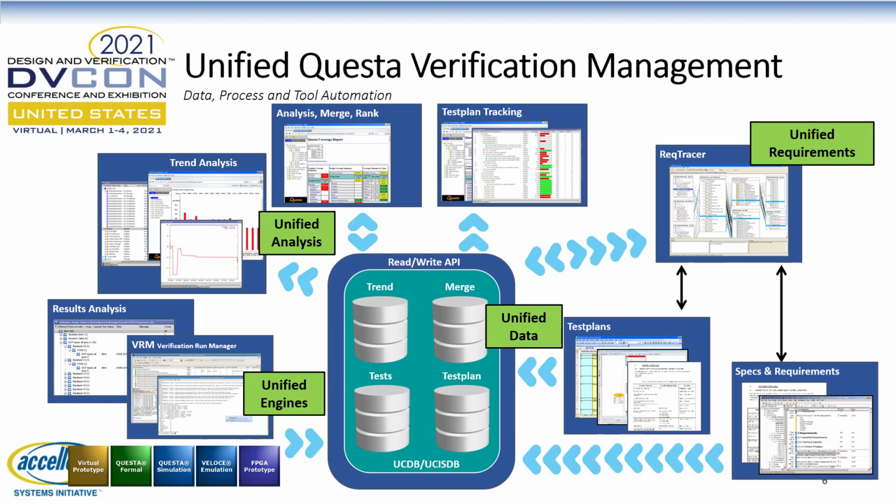And it also correlates elements of your verification environment to determine if that RTL element has been properly tested to satisfy the original requirement. The verification element can be a test, or it can be a SystemVerilog covergroup, or an assertion, or a UVM sequence, or whatever you need it to be. Since everything is linked back to requirements, you have a built-in ability, if you make a change to your RTL, to know which tests have to be run to make sure you didn't break anything.